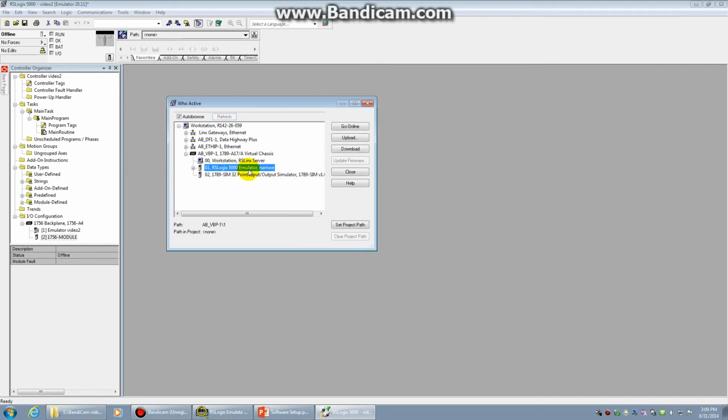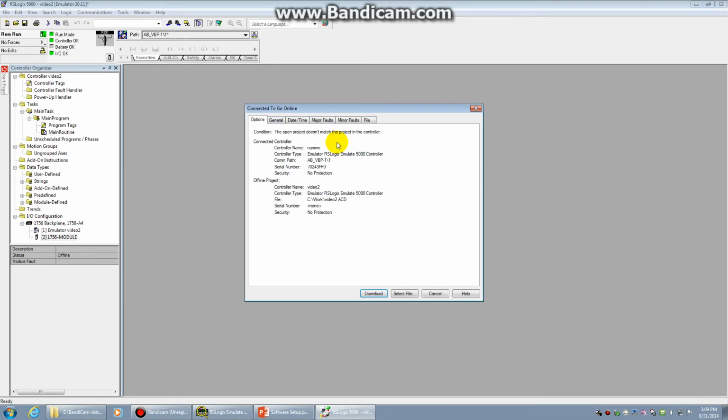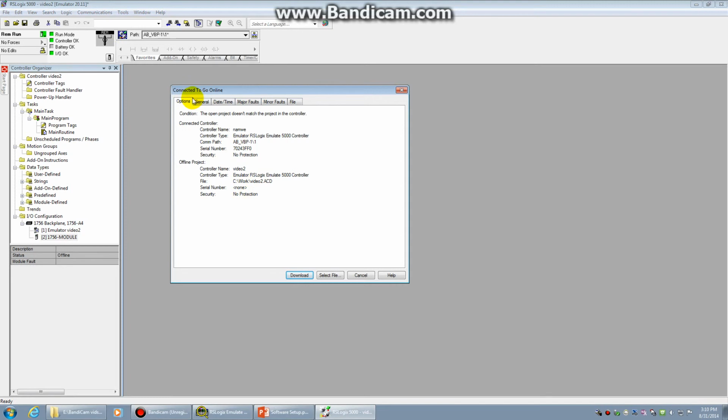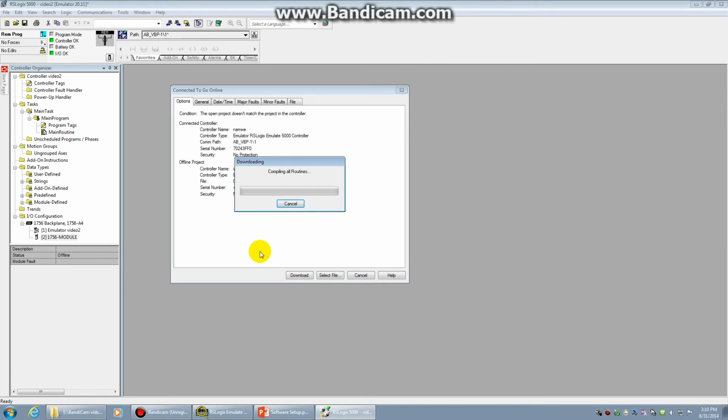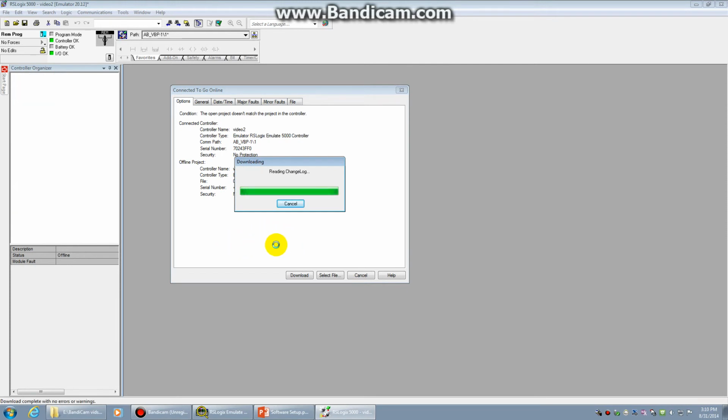Of course, I changed the name, so when I go online, this name will actually change to Video 2. This was just a previous test. Click Go Online. All right. And then you're going to want to select Download. And this little warning sign here, if you were programming a live PLC in a plant, this is just to make sure that you took all the hazard conditions into your calculation before you kill somebody on the plant floor. So go ahead and hit download, and it's going to compile this onto your controller.